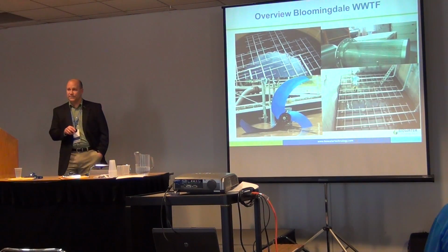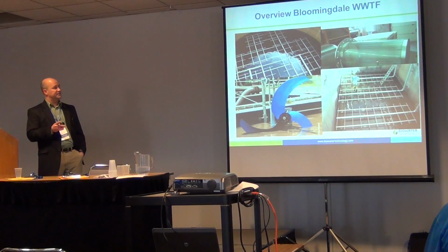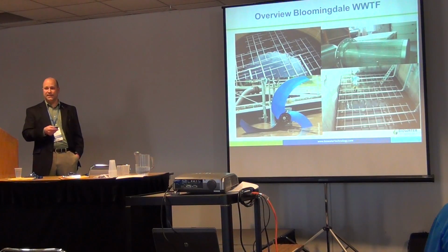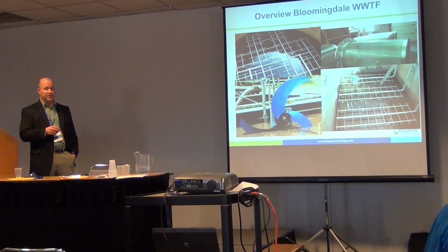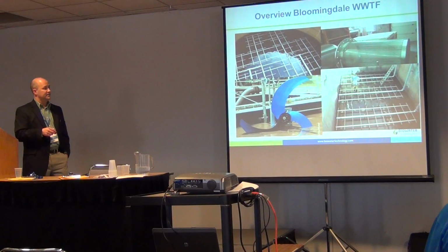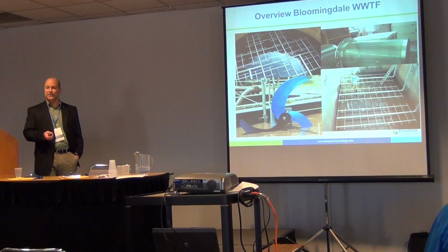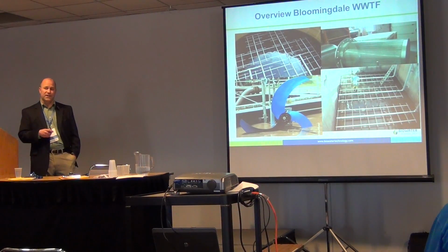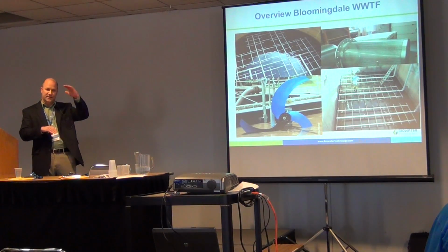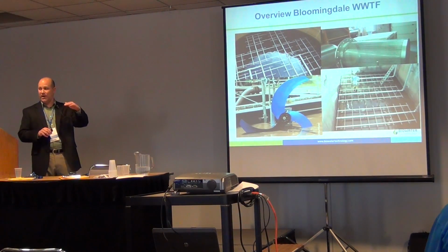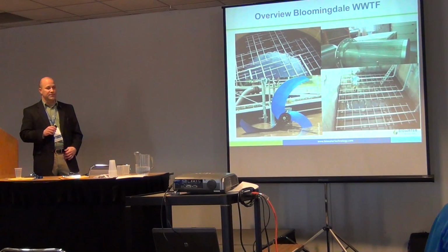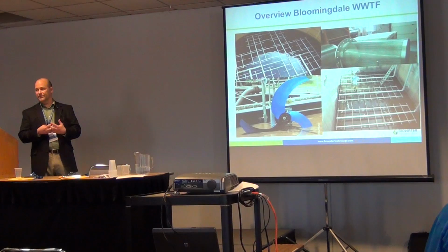So the way the aeration grids get designed is from really two stages. One, you have to get the correct amount of oxygen into the tank so that you get the BOD reduction and nitrification to happen. The second is you need the correct amount of activation energy to actually move that media around the tank. Depending on the application, you could go down to as low as a 25% fill fraction. So out of that tank volume, you'd fill up 25% with the media. And that's to make sure that there's enough media that they're colliding with each other.